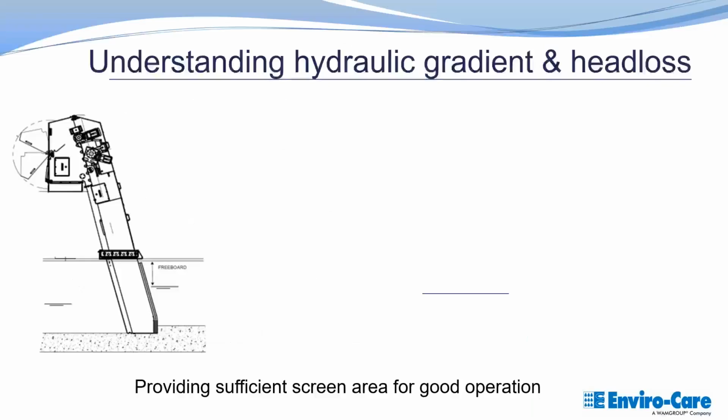But first, let's talk head loss. Head loss is frequently misconstrued when it comes to designing a headworks, because head loss through an orifice or through a pipe or something of that nature is very easy to calculate. It's a set amount of restriction. There's a set amount of driving head required to get a flow rate through it. It's very straightforward. The screen starts that way.